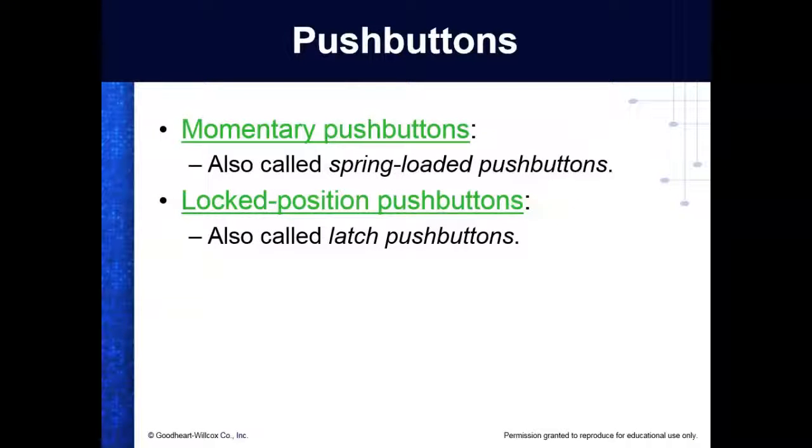Momentary contact push buttons, that's what these are up here on this trainer. Most push buttons are what we call momentary contact, which means what? Well, they could be normally closed or they could be normally open, but they're momentary, which means they have a spring in them. They're in one state, either normally closed or normally open, and they change states when you push on them, but as soon as you let them go, they go back to their original state.